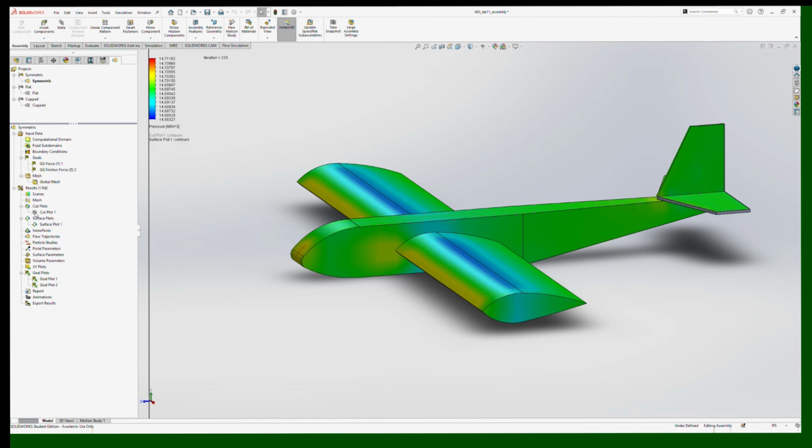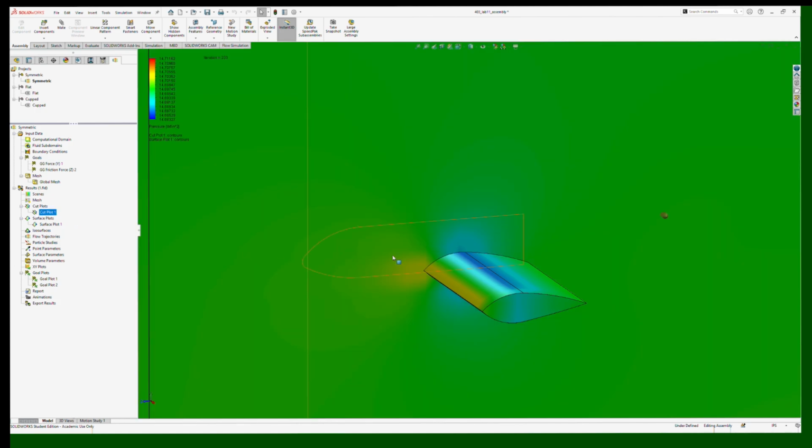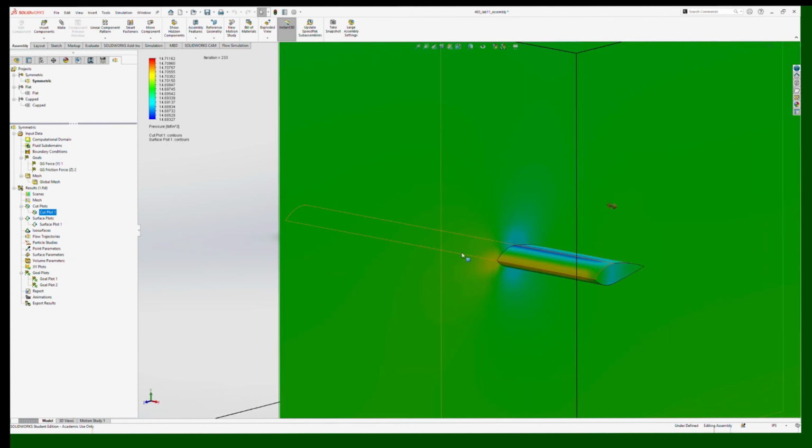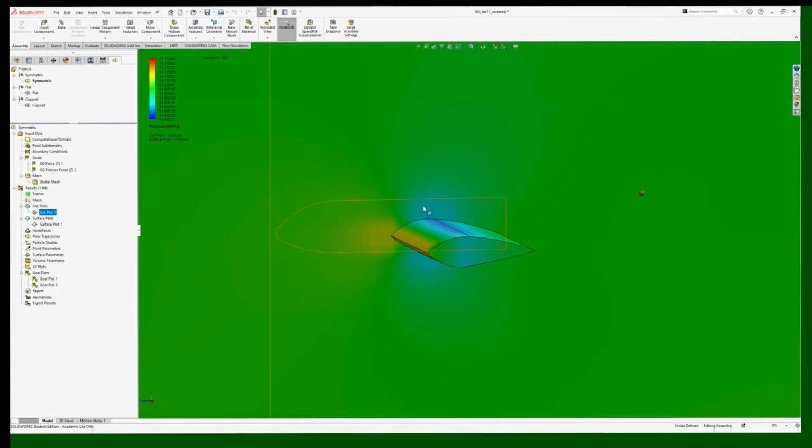And if you want to look at this pressure distribution in more detail, we can also look at a cut plot of specific sections of our wing that shows us where the main pressure zones and the direction of airflow will occur in the cross-section area. As we can see here with the symmetric wing, really not much of a difference. There should be no difference on either side of the wing. It's fully symmetrical. The only difference might be due to gravity and how that's affecting the actual air. So let's hide that.